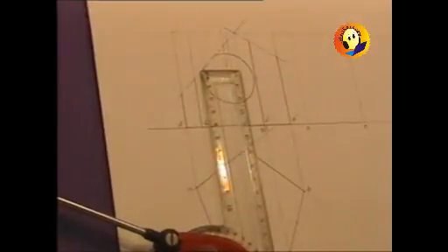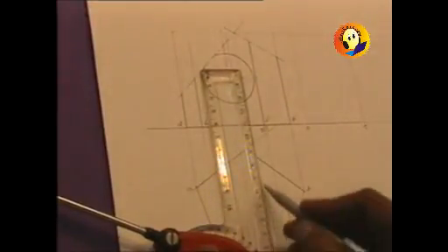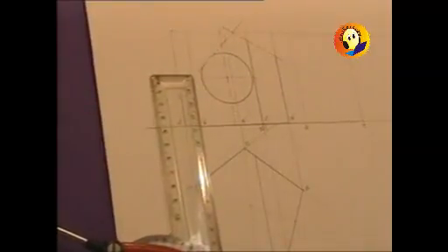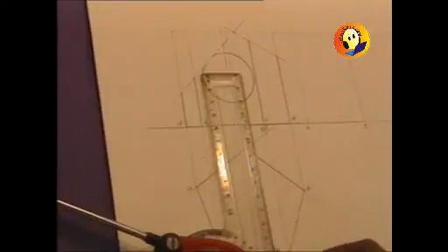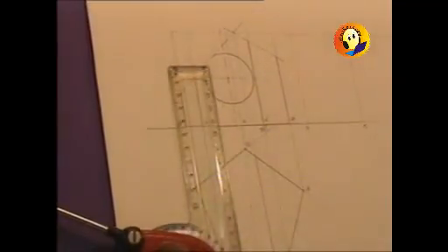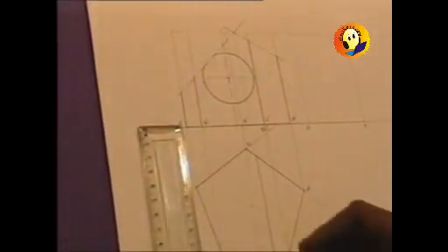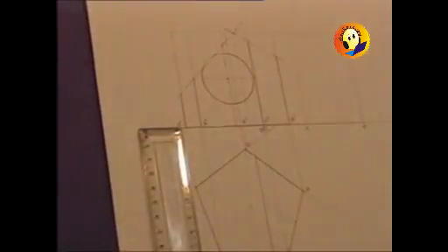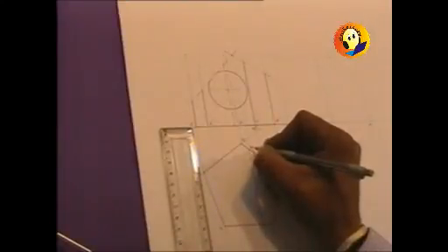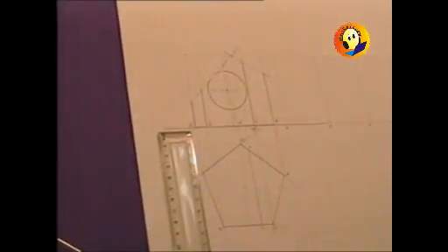So the section plane is actually, 2 planes are cutting at this particular line. This is the line of intersection of the 2 sections. So the points can be named as point number 1, which is on BC, and point number 2, which is on DE. These 2 generators can be easily marked so that I can complete the first part, that is showing the section planes.